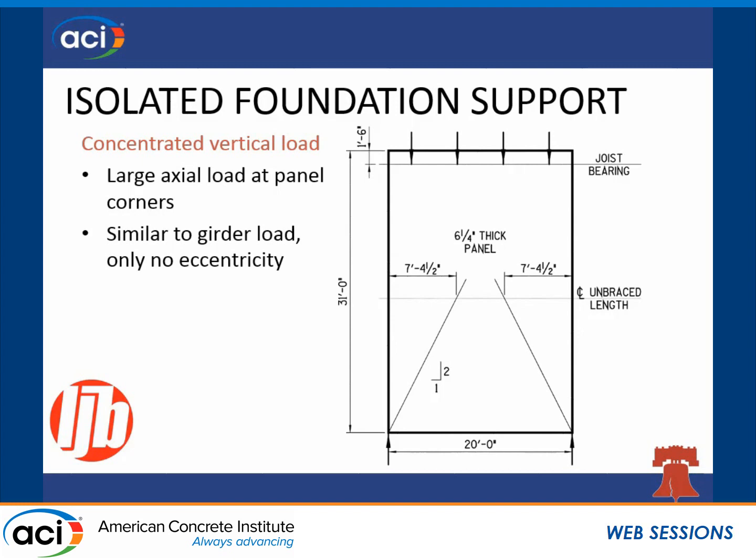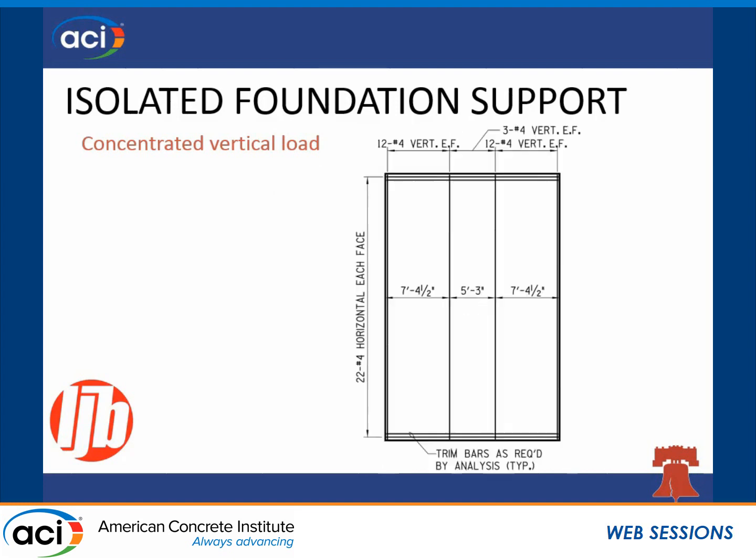you can see at our center line of our unbraced length, we actually have less of the panel to count on. And you can see in the end product how we concentrated more reinforcement into those legs and just use nominal reinforcement in the middle.